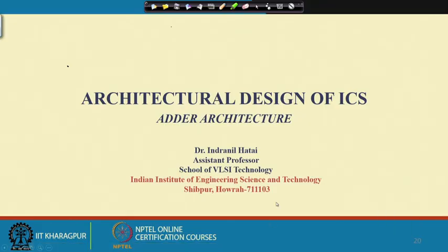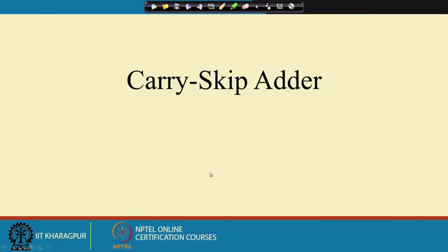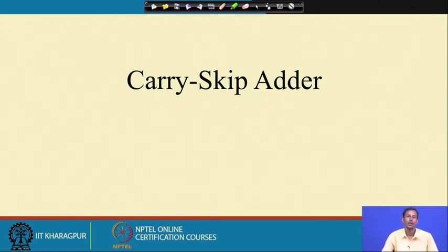Today we will see another architecture, which is the carry skip adder. By its name, it says that we can skip the carry. Where and how we can skip the carry, and what the usefulness of skipping the carry is when performing the addition operation, we will see in this lecture.